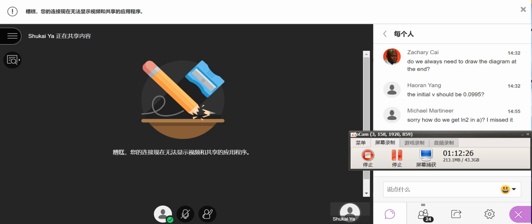We know that omega n1 is equal to the square root of k divided by m, which is equal to 2 pi times f. Omega n2 is equal to the square root of k divided by (m plus m0).